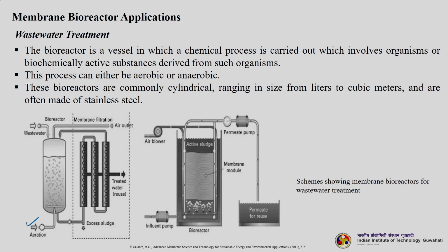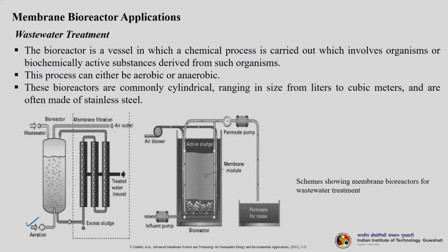And membrane filtration in terms of tubular systems you can have, or different types of membrane contactors can be used, HFMC can be used, plate and frame type also can be used. Okay. So, the process can be aerobic or anaerobic, it does not matter, both can be fine for the membrane bioreactors. They are commonly cylindrical, ranging in size from liters to cubic meters and are often made up of stainless steel.